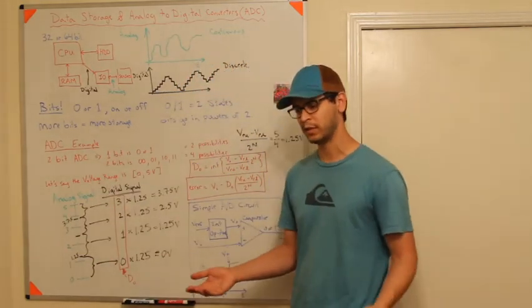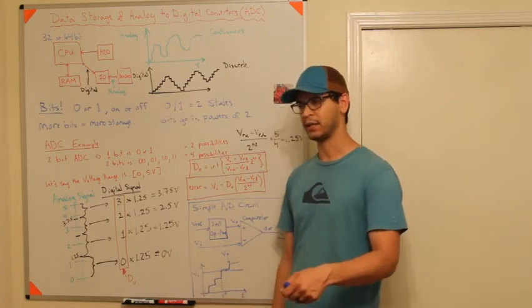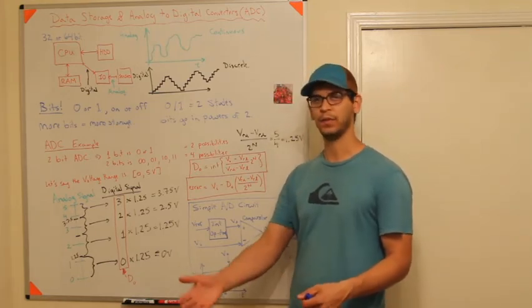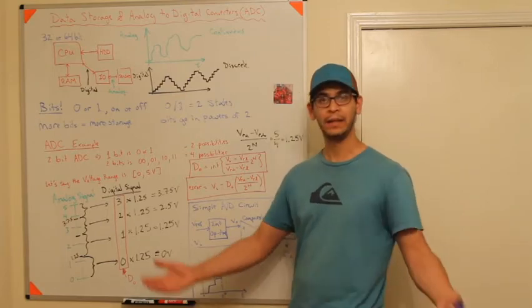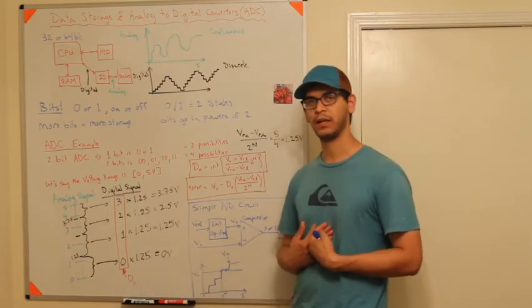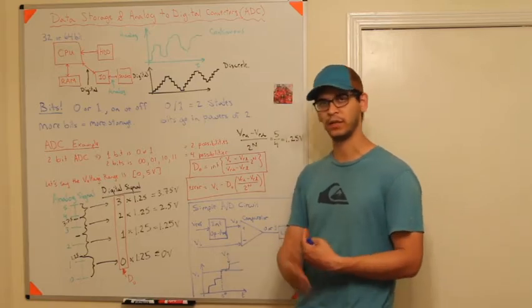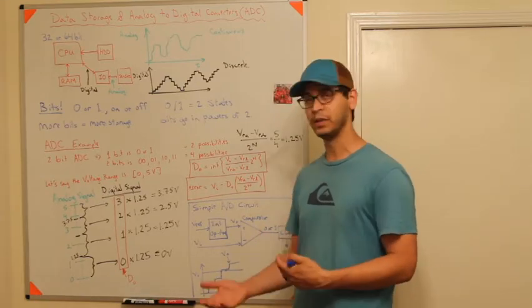So I'm using an Arduino, I can hook up an analog sensor to it, and the analog sensor is going to output 0 volts, or it's going to output 5 volts, or anything in between. My computer, on the other hand, can't read that analog signal, so I'm going to discretize it into 4 different categories. Now, I'm going to lose information, right?